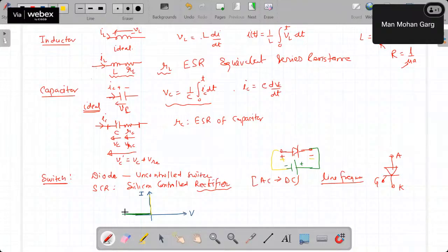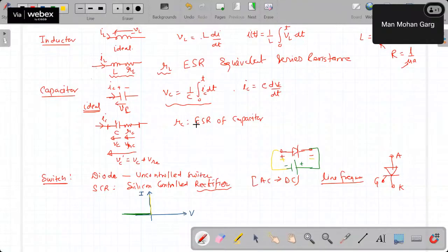We see that whenever we apply a positive voltage across this, there is a depletion layer, right? So that depletion layer width will be reduced, and it will take some voltage, maybe 0.7 volt, maybe 1 volt. Then after that, conduction will start slowly, and it will go like this, right? And even after this 0.7 volt, which we call the forward voltage drop, this is not a straight line, right? It will depend upon the internal resistance of the diode, and accordingly this slope is decided.